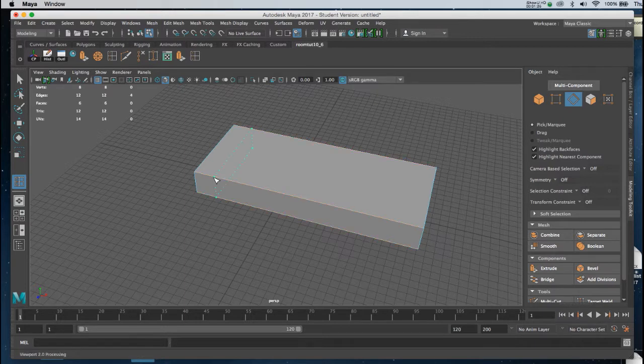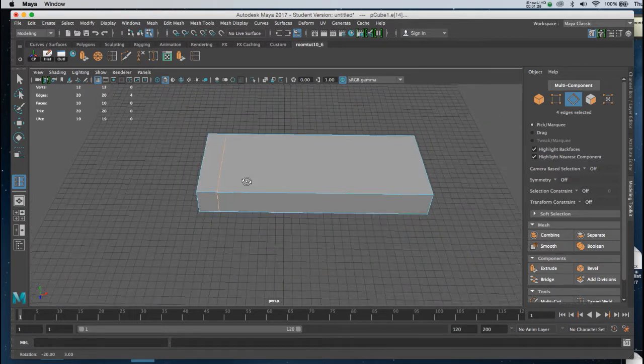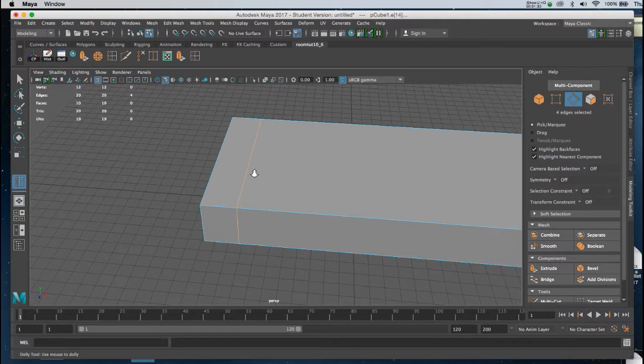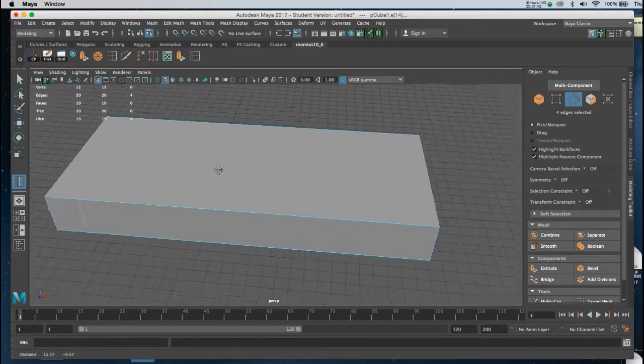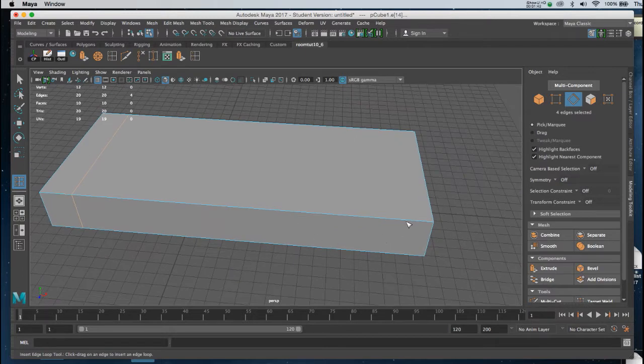I'm going to click and drop an edge on the left-hand side. And what I did was, when I clicked on the edge, it gave me a new edge perpendicular to the original, going in the opposite direction. I'm going to go down to the other end of the rectangle and do the same there. I'll click, and I can reposition it with the mouse before I let go, or I can use my Move tool, and when it's brown, I can move that as well.